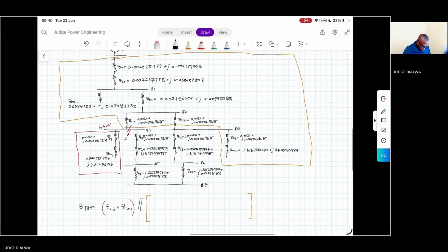Okay, and what is that? We'll start off with cable 6. We have the series combination of cable 6 and our condensate pump motor, motor 2. This is in series with the impedance of cable 2, and all this is in parallel with everything upstream of bus B2.